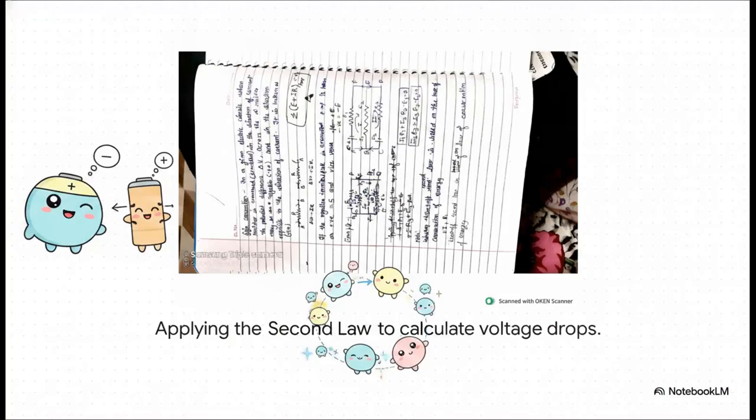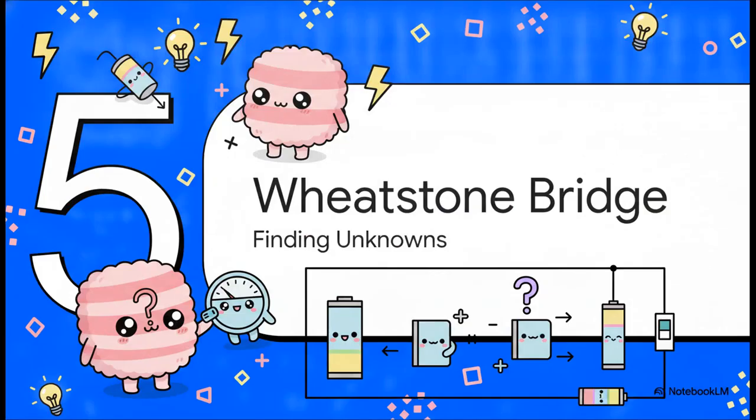Now, applying Kirchhoff's second law to navigate closed loops is incredibly cool. By using strict sign conventions, we can traverse complex networks to solve for completely unknown currents. When we travel in the exact direction of the current across a resistor, we mark that potential difference as negative. And if we hit a battery's negative terminal first, we take the EMF as positive. Carefully, and I mean very carefully, tracking this around any closed loop ensures the sum of all voltages definitively equals zero, every single time.